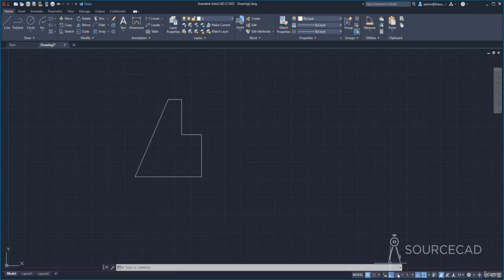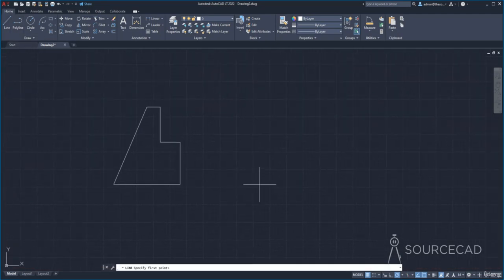So I'll just activate polar mode, and as soon as I activate the polar tracking mode, it will automatically deactivate the ortho mode. Okay, so with that, let's go to line, and now if I make a line, it will create this kind of green tracking line when I'm perfectly horizontal. Now that's because of polar tracking. So it will show you when your line is horizontal. Not only that, if I move it in this direction, it will show you that 90-degree angle as well.